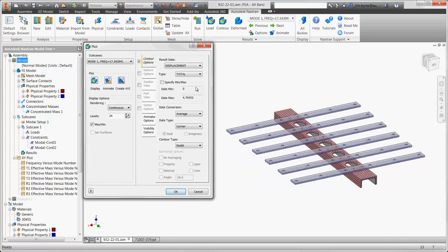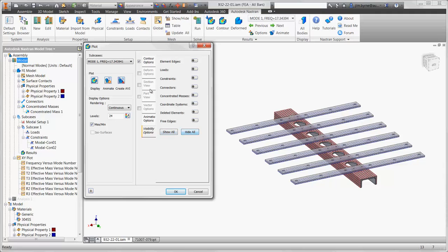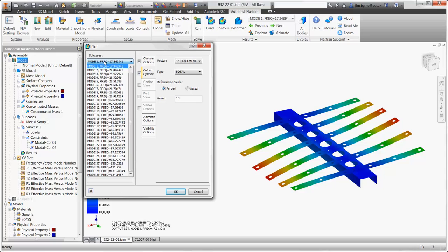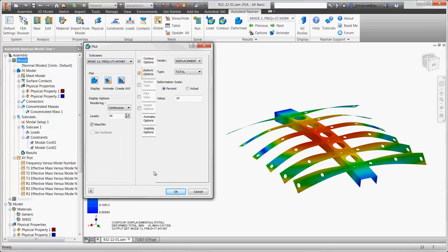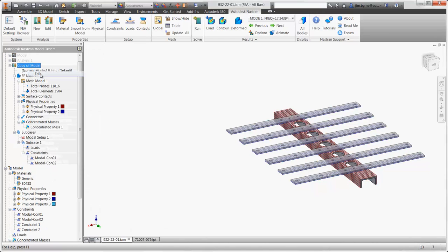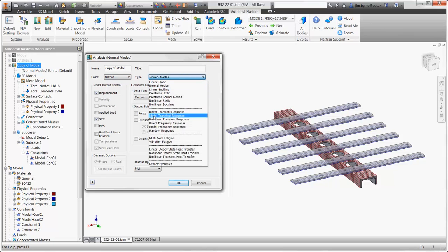The first natural frequency is now down to 17 Hz with the added mass. This may be a concern since the model tends to vibrate in the same direction as the motion in the machine. We can dig a little deeper by applying the actual velocity or acceleration to the model. Let's change the study to a transient response type.